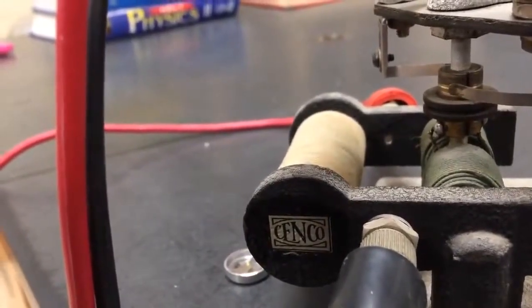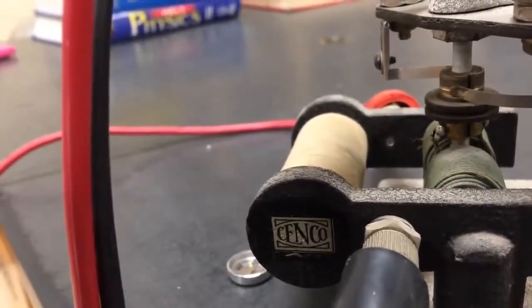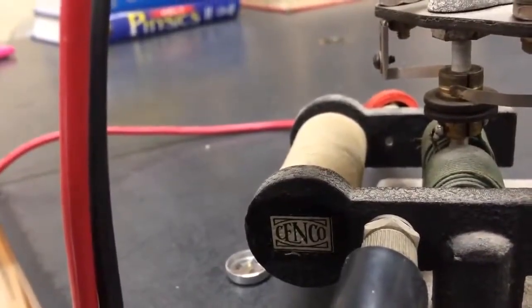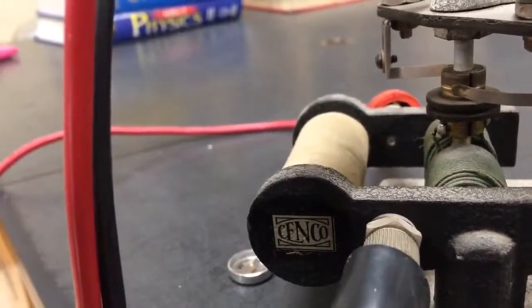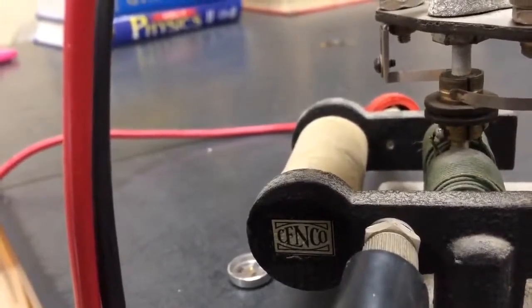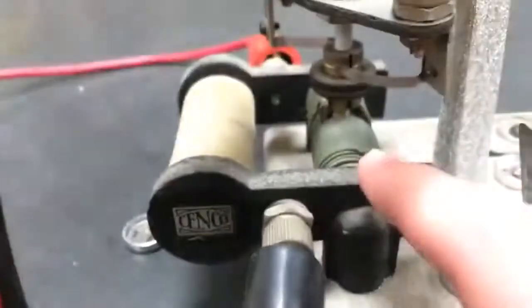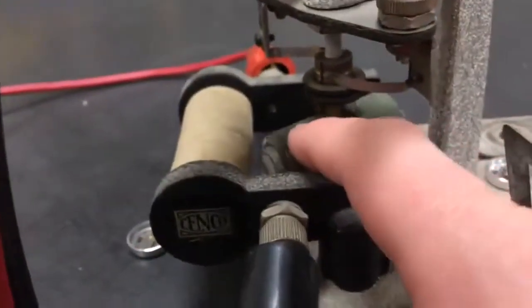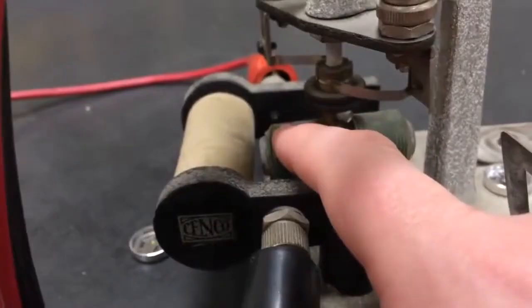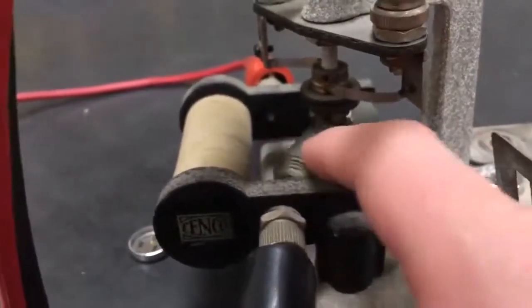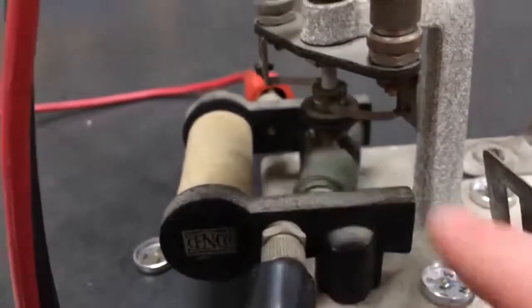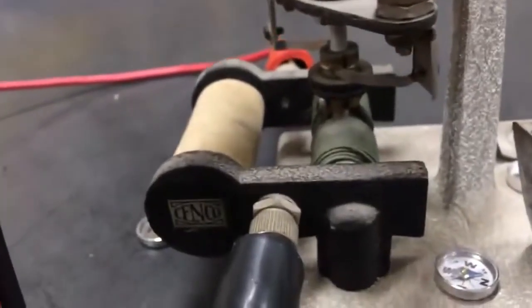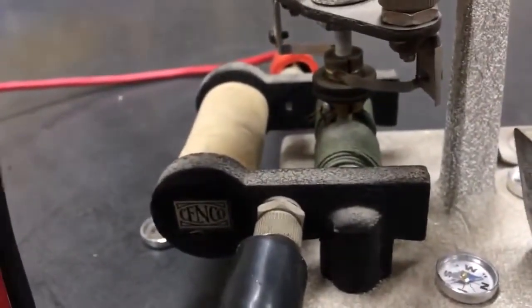And that means the coil is reversing the direction of its current, just as if it was alternating current. And that means that we're always getting pushed in the right direction because after we've gone around once, it flips, current reverses, so now it continues to push in the direction we want. So it's on all the time instead of half the time, like the previous motor.